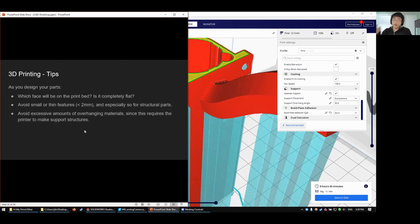And we'll talk a little more about what I've seen in printing, what sort of things you should keep in mind as you print and as you design. So specifically as you design, consider what face will be on the print bed. Is it completely flat? If it has raised edges, or curves or stuff, it's going to lift it off the print bed. If there is, there's going to be more support needed then. So consider that as you design your parts.